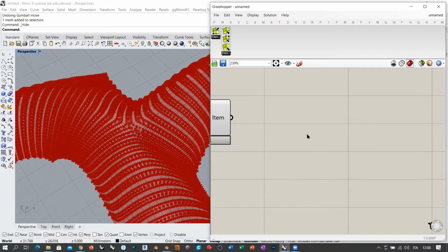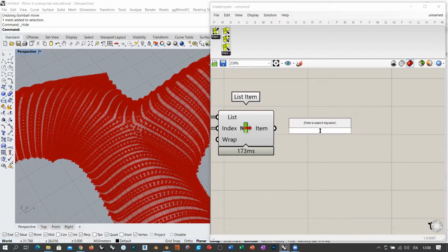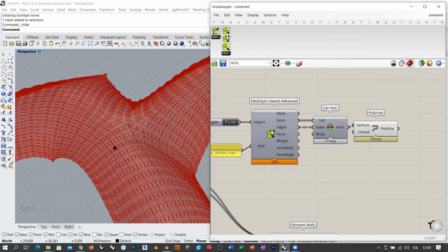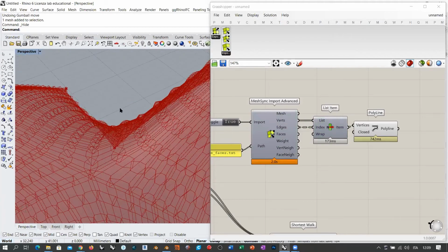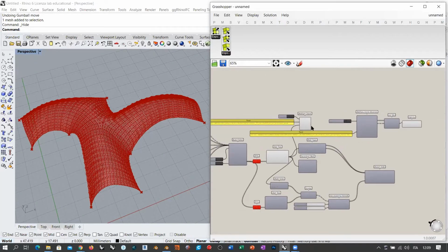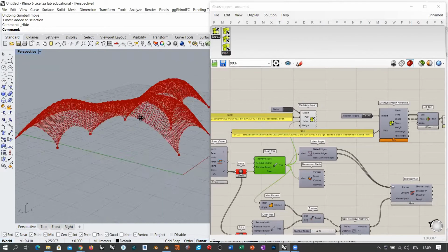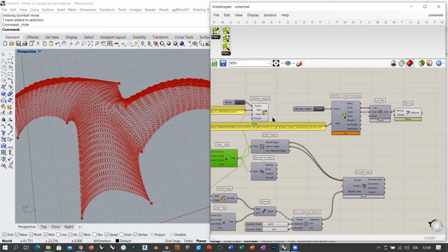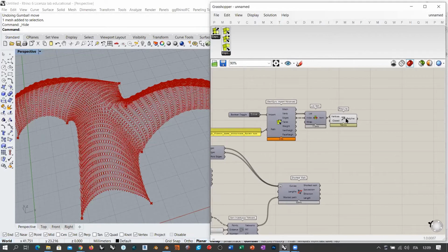So a couple of points, how do we connect them with a straight line with a polyline segment? So if I do this, finally, if we hide all the vertices, all these vertices, we get our structure made up only of lines. Okay. So I no longer need to see the result of kangaroo mesh. I have my base structure here of lines. Remember that this is only visible as long as you keep this to true. Okay, so if I stop importing this, then everything here will become empty, of course.